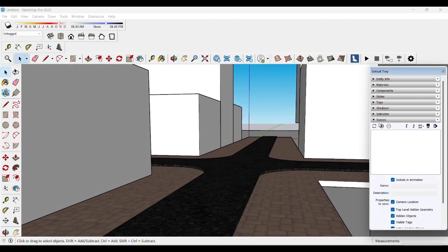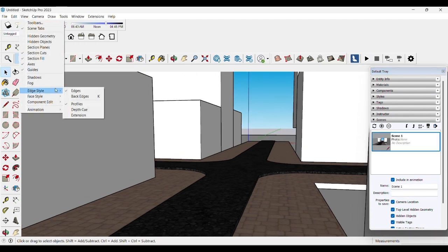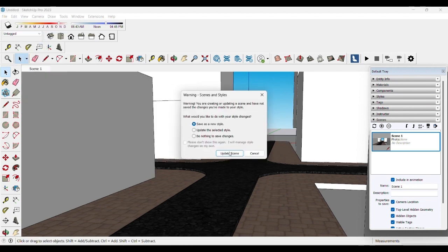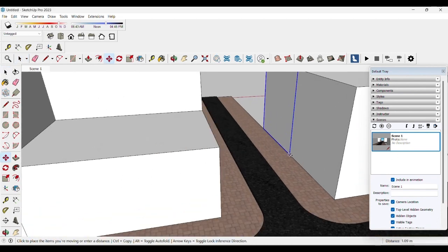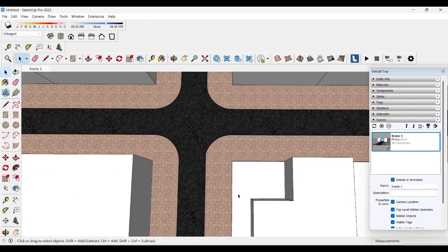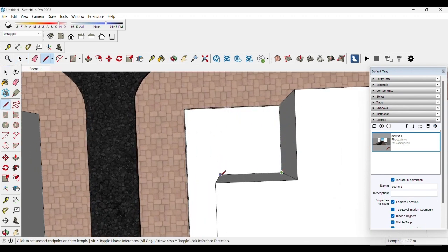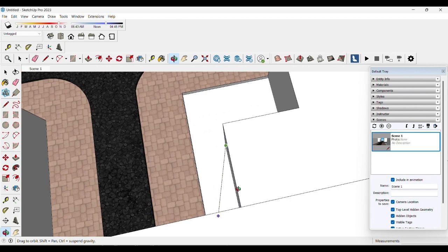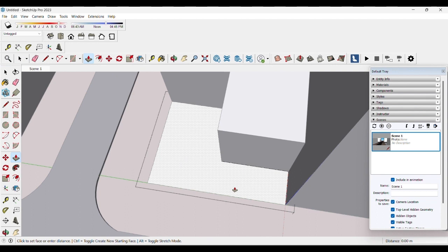We'll create scenes, so I've added one scene. We can reduce the edges by clicking in this section. Now update the scene again, and the lines are much lighter in that setting. Let's give a material surface under this opening with the line command. L is the command for it. Create a surface. Create the surface and give a thickness by using push.